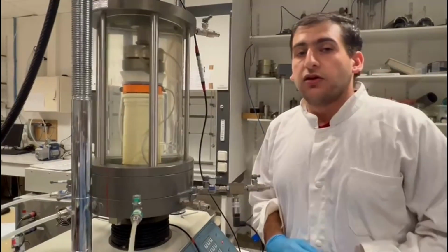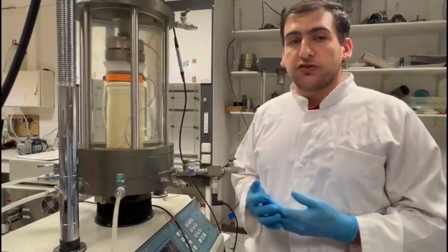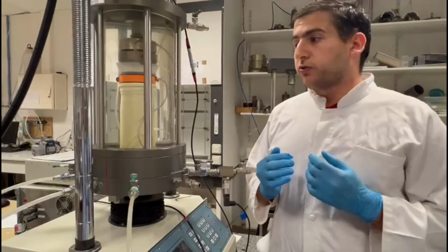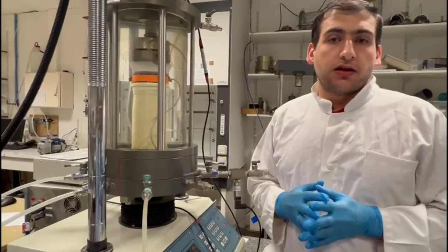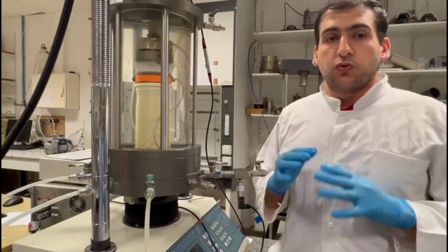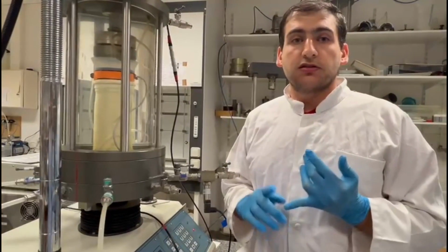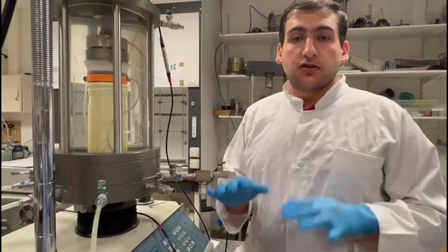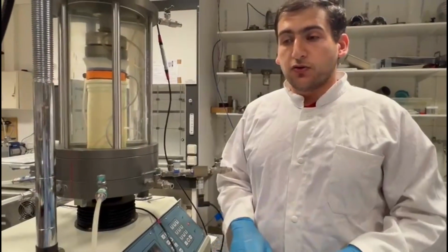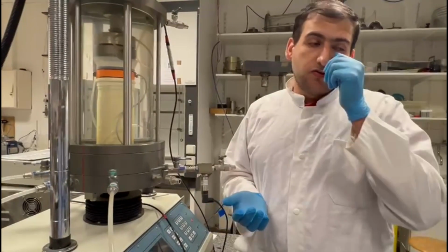We already know that there are different methods to solve this problem, but we have to understand when it happens, why it happens, what are the factors that we can play on, and how to avoid this liquefaction phenomenon. For example, we have the saturation degree, how much water there is, how much air there is inside the soil; the confining pressure, the consolidation, how much our soil is condensed; and the density of the soil also.